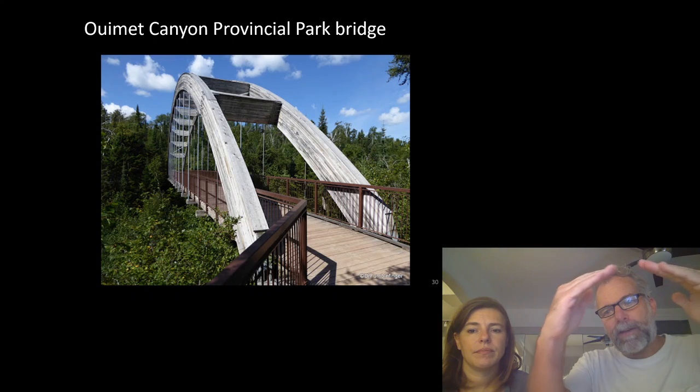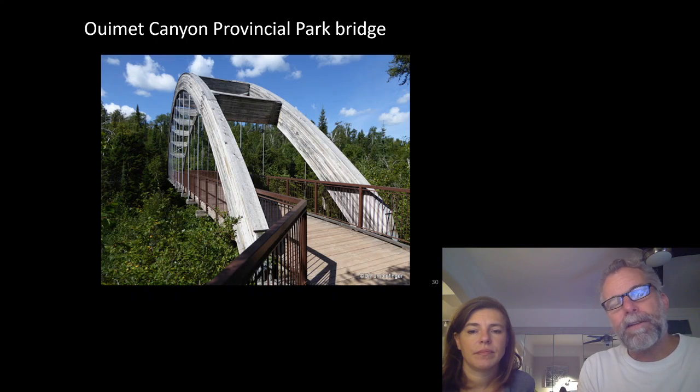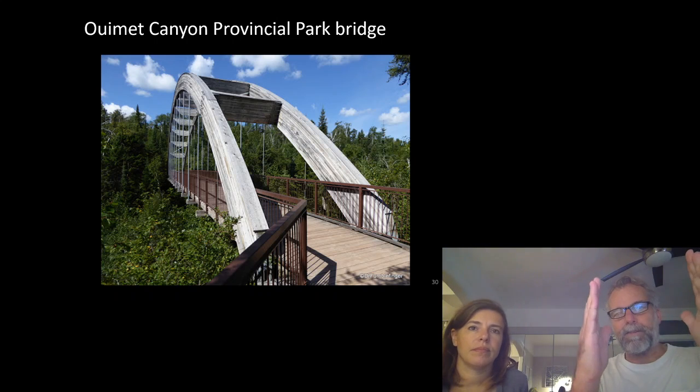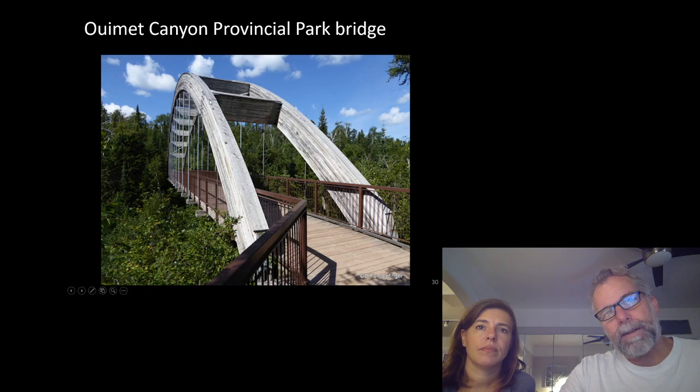We have the funicular arch, but we also have the bending stiffness, and that's what gives the arch its overall stiffness. Shannon mentioned this in the context of the covered bridge, that if you've got an upstanding element with compression on it, there's a potential for buckling. So arches are connected together with these deep webs, which stabilize it laterally.